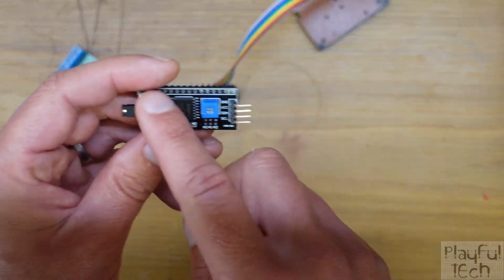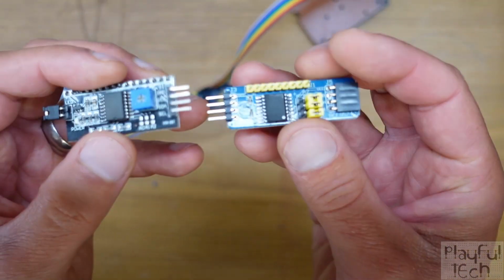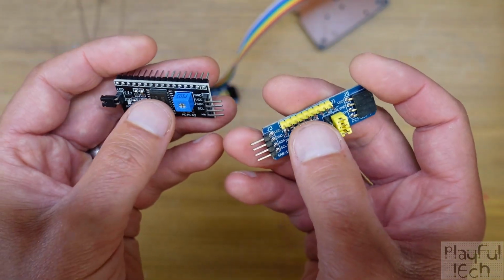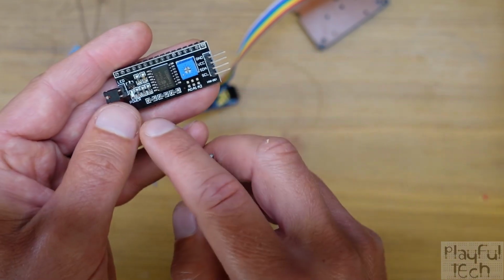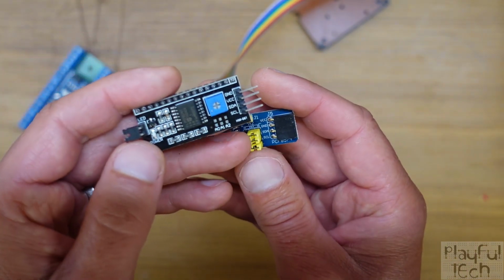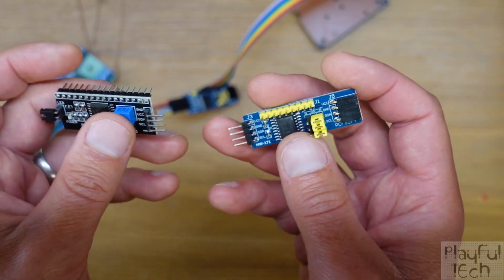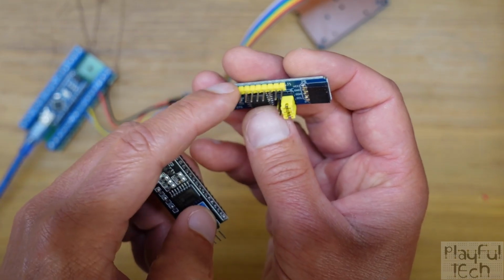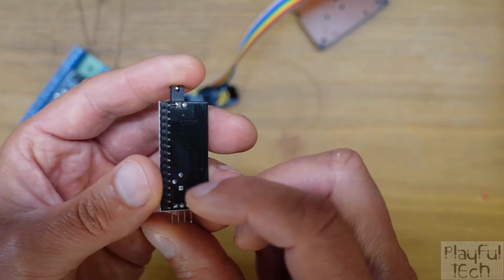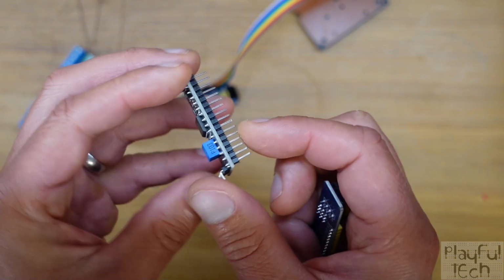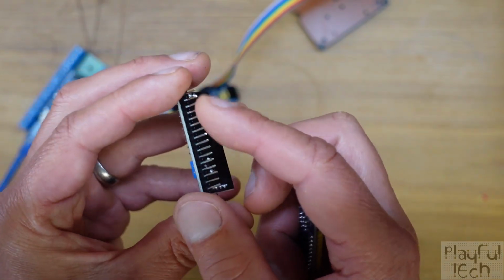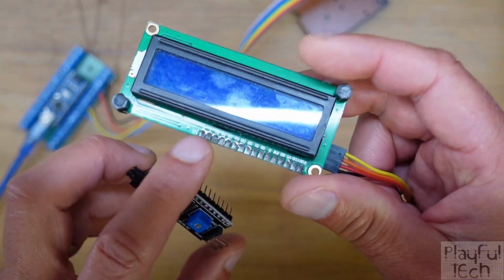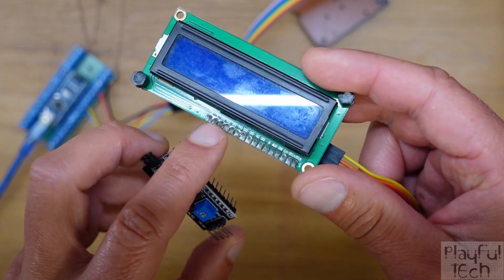So functionally, this board here is exactly the same as the first module I showed you. It's still got the same PCF8574 port expander chip. It's got the ability to select from one of 3 addresses. The only difference is that it's been laid out slightly differently. So instead of having just 4 general purpose pins across the top, it's had the outputs from the port expander mapped into a row of 15 pins here that line up with the 15 pin interface that you get at the bottom of an LCD display.